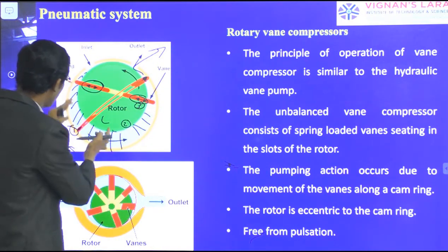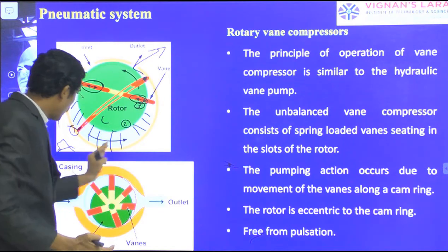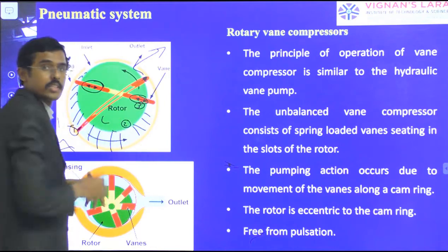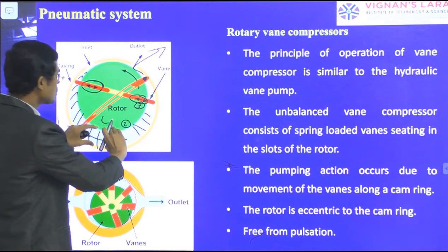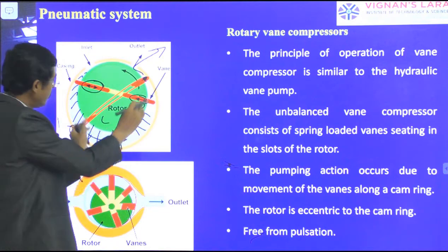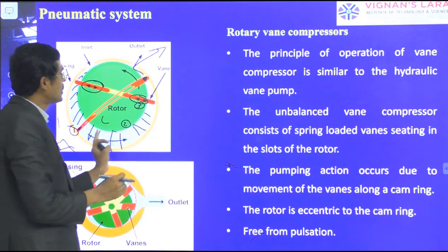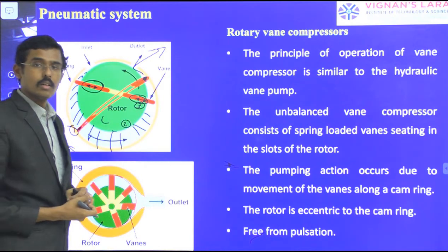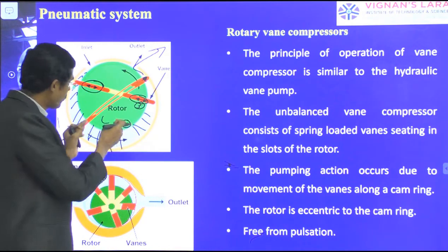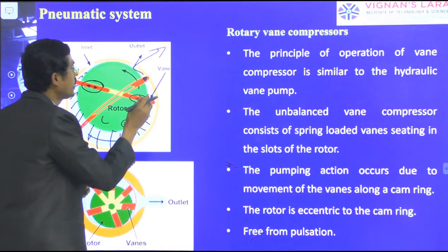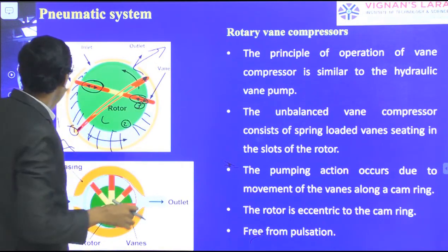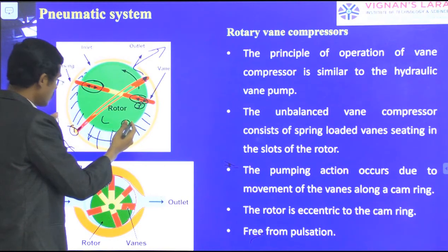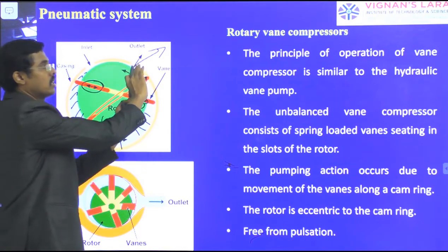Here we have high volume, the shaft is rotating and it is not finding equal space. Therefore, the air is compressed by itself within the space allotted and it is trying to escape when the outlet port comes. What happens? Compression takes place here. Therefore, we are getting more pressure at the outlet. Normal air comes in, volume is occupied, spring return, space reduction, then compression, and it goes out.